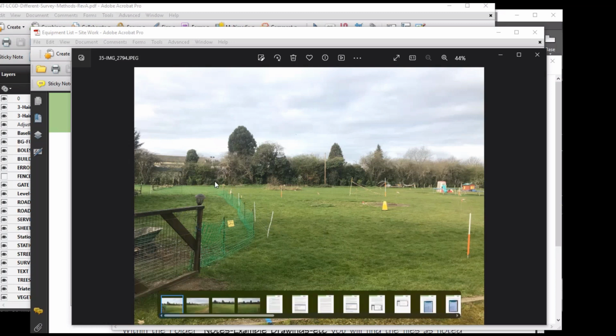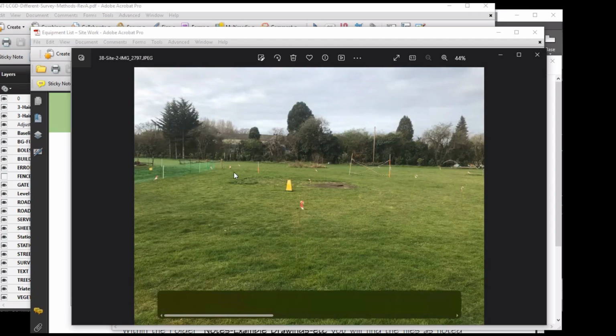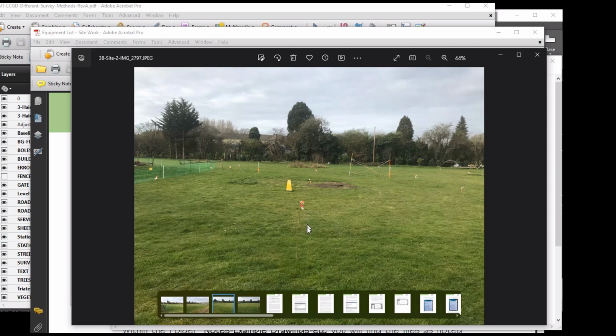you can see the mouse, and then an electric fence going round the side, a ranging pole over there, which is the corner of our 5 metre level grid, another ranging pole there, which is another corner of the 5 metre level grid. Then these 2 poles up here are a fictitious fence I've got, and behind that cone, and the other cone over there, and the other cone over there are survey stations. And you can also see the bamboo canes that I've set out, the 5 metre grid, 1, 2, 3 and 4. And again, I've got them coming back here, 1, 2, you can see. And then there's an IC there that was surveyed.